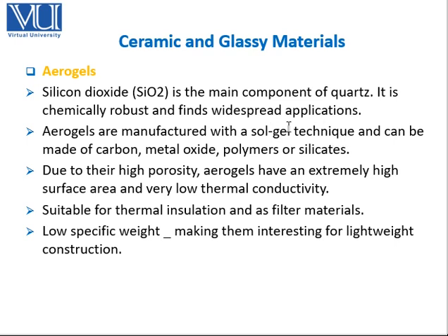So aerogels are made through sol gel techniques and can be made of carbon, metal oxide, polymers or silicates. Due to high porosity, aerogels have an extremely high surface area and very low thermal conductivity because there are pores in the aerogels. So due to this property, they have high surface area, and that's why they have very low thermal conductivity.